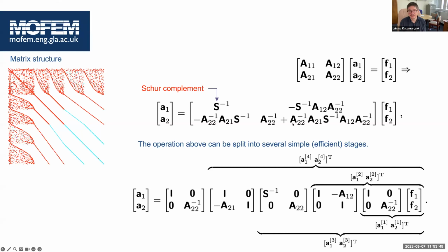And then again, you're applying the Schur complement, and the Schur complement is in fact one way of multiplying your system by sparse matrices. But because those fields are in L2, you can do it on an element by element level when you're calculating this inverse, this one and that one, on the element using, for example, LAPACK, and very small matrices, so you can do it very fast.